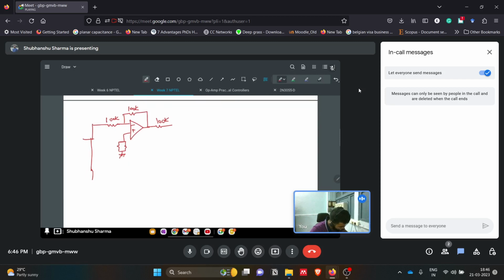And we'll make one integrator circuit here, that is a capacitor in the feedback. We will have 1 mega and C1 1 nanofarad. So based on the values of these two, the time constant of this integrator will be decided. Error input. This is 100k here.